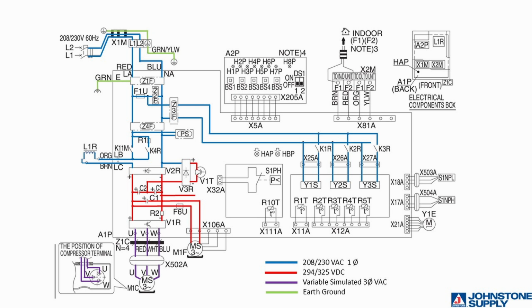Sometimes the AC power entering the outdoor unit contains noise that is picked up through the transmission lines on its trip from the power generating station. To ensure the system runs at its maximum efficiency, the first thing that the power sees is a noise filter section, which removes white noise and harmonics from the incoming power. The cleaner the incoming power, the more efficiently the system will operate.